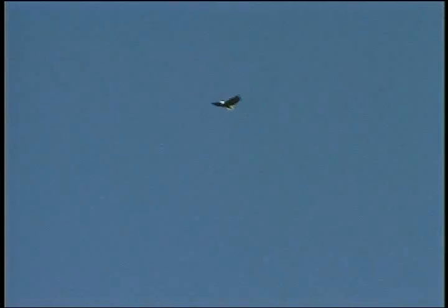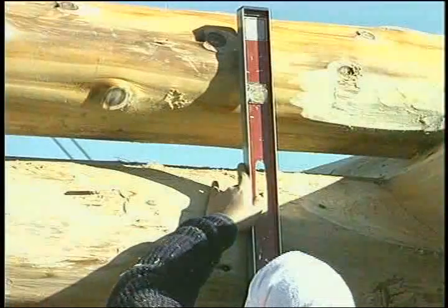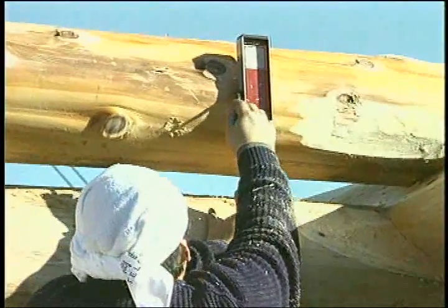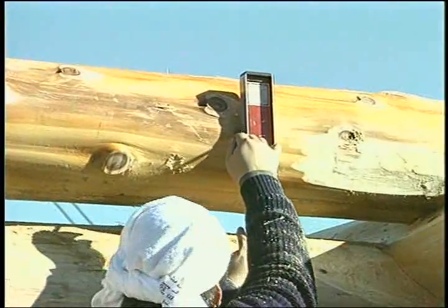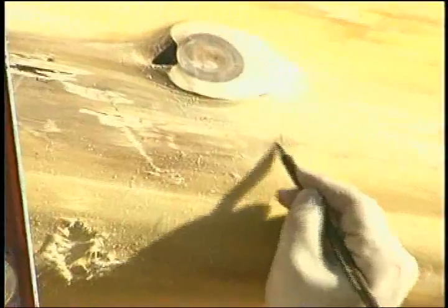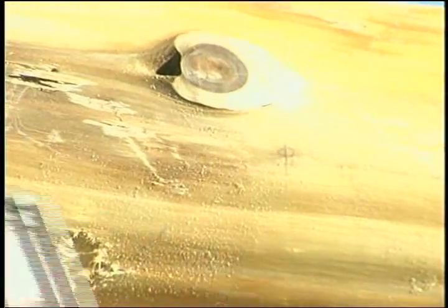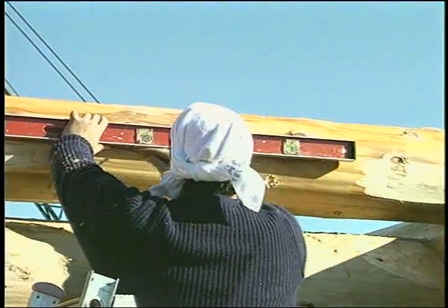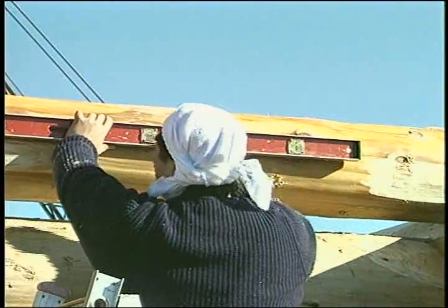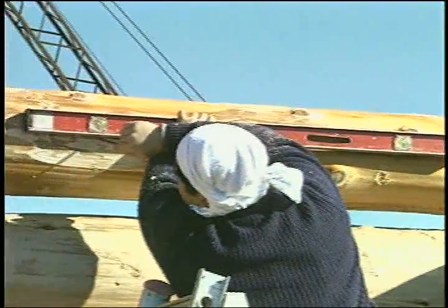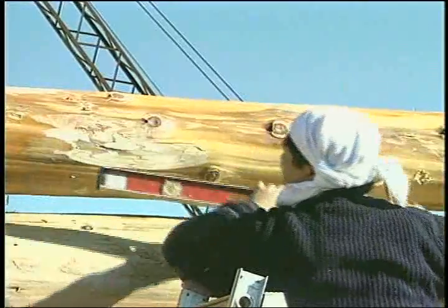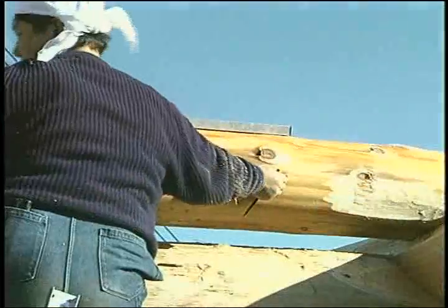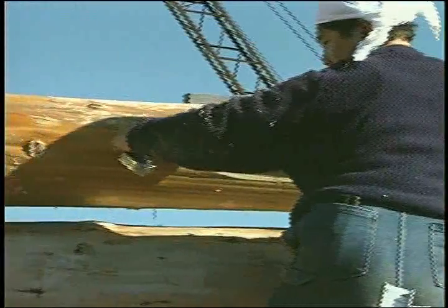Mark the exact cut width onto the header log. Then extend the height measurement that you have already located to intersect this mark. Use your level to draw this height to the other side of the window, or better yet, snap a chalk line at the header height after you have measured in the exact window width.